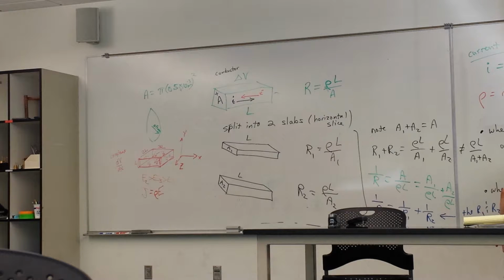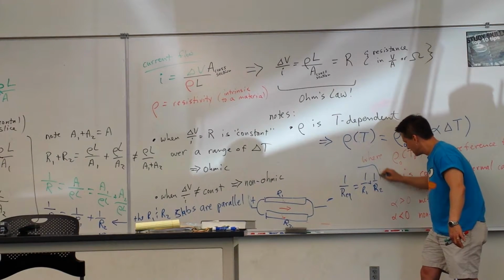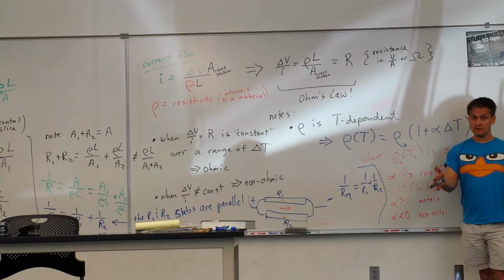And if this is R1 and this is R2, if we connected them so we could run a positive voltage across them with respect to the other end, then the total current that flows between I1 and I2 is related to this: I2 R2 is V, I1 R1 is V. The inverse of the equivalent resistance between R1 and R2 is equal to 1 over R1 plus 1 over R2, between the two endpoints.